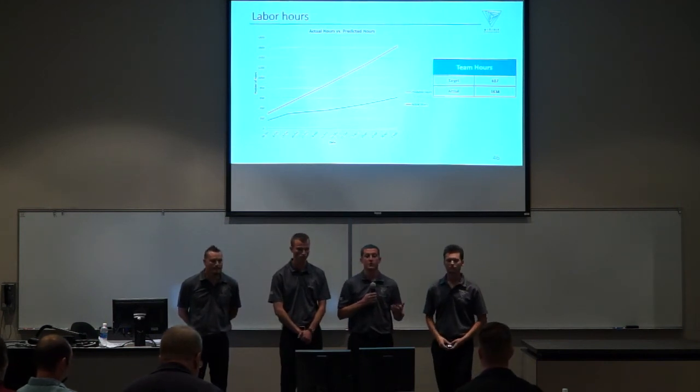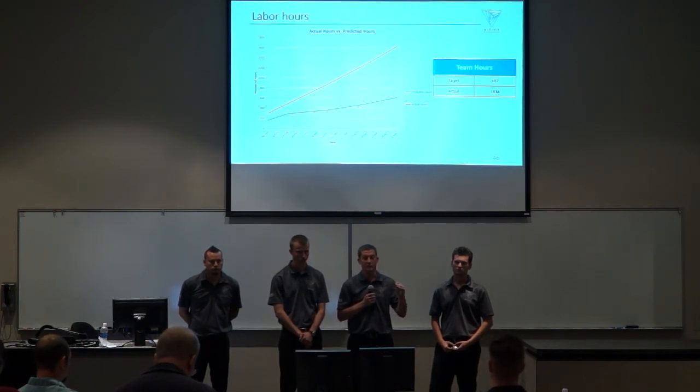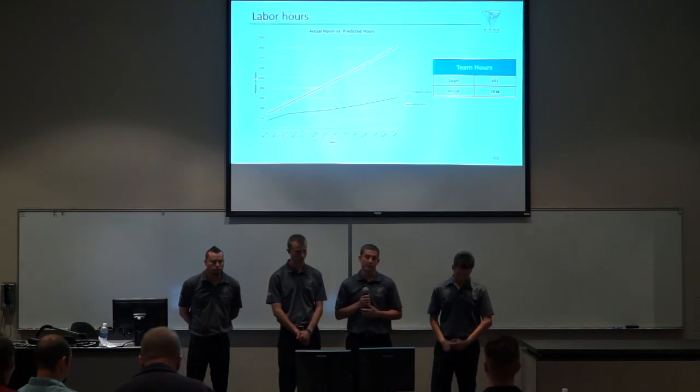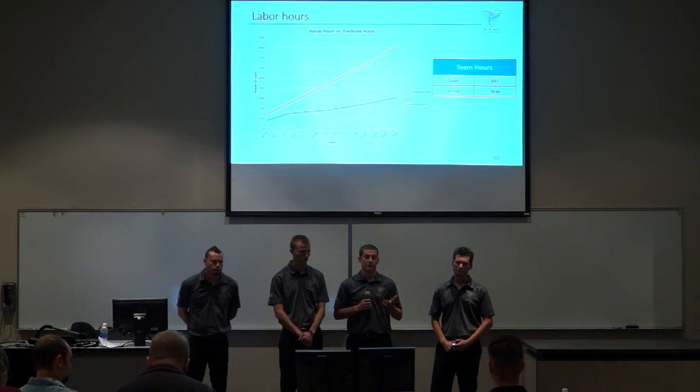What do you mean by noise? It's mostly the total voltage drops. It would drop to absolute zero signal. Those were really easy to distinguish looking back at the data later. To fix that, we would definitely go with a printed circuit board in the future. Since it was on a breadboard, there were connectivity issues. When the system started vibrating, you get random voltage drops. So making those actual hard connections in the future would be ideal.